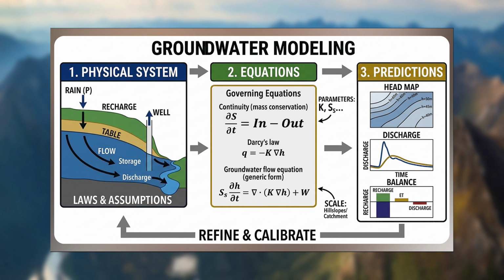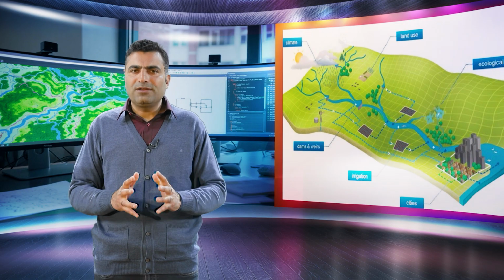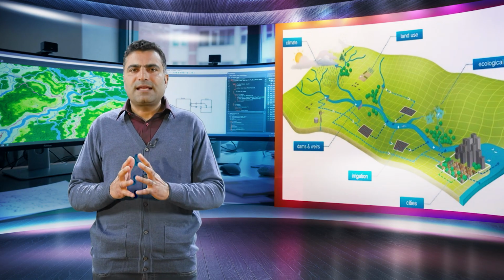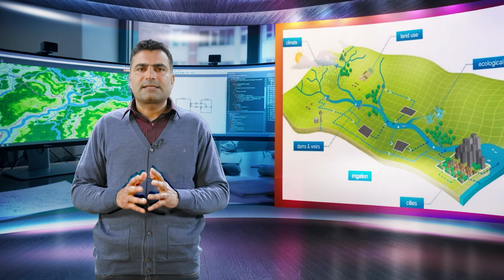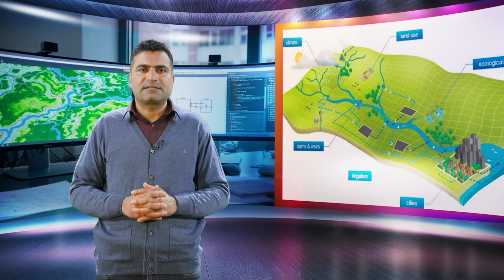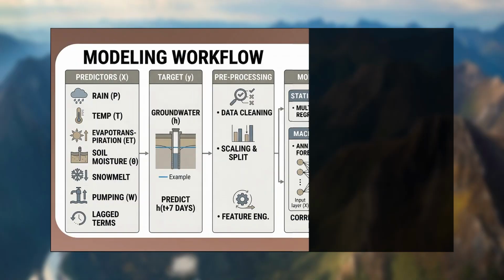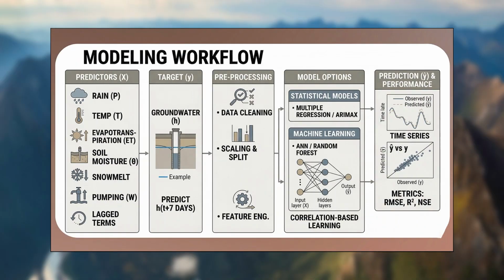These models are classified by their approach to underlying physics. These models utilize empirical or statistical equations which are formulated from existing data to assess the system response to various inputs, such as how precipitation can lead to a rise in water level. They do this without explicitly quantifying the underlying physical processes or properties of the system. An example is using an artificial neural network, that is ANN model, to predict water levels based on historical weather patterns.